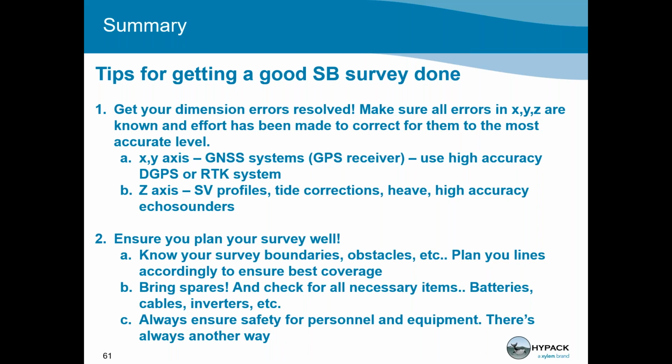Okay, there's a SonTek question here which I could probably answer. What's the best River Surveyor upgrade to HydroSurveyor if you are interested in cross sections of rivers? And the answer there is you do not need HYPACK or HydroSurveyor. You could do the cross sections within the River Surveyor Live software, and you're able to export the XY, the lat long, and the depths, and develop your cross sections that way. HYPACK's obviously a lot more complete in terms of setting things up, but if you're only after cross sections, I'm not sure I would recommend going down the HydroSurveyor path.